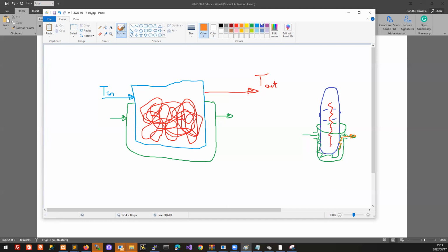In our reactor, this is a flow reactor, so there's an inlet stream here, into the space and out of the space. That's our reactor flow. And then things heat up in there. So here we've got T in reactor, and coming out, we've got T reactor. I'm just saying T, not T out, because remember, if we regard this as a CSTR, then it's perfectly mixed. That means your exit temperature is the same as your temperature in the reactor. So I'll just call it TR.